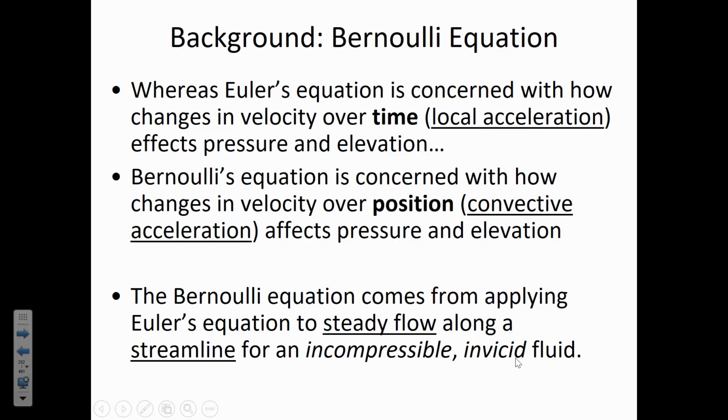So when you see mistakes in how well Bernoulli's equation predicts what you actually observe in the lab, those mistakes, or Bernoulli's shortcomings as a model, are going to mostly stem from the fact that your fluid isn't incompressible and it's not inviscid.